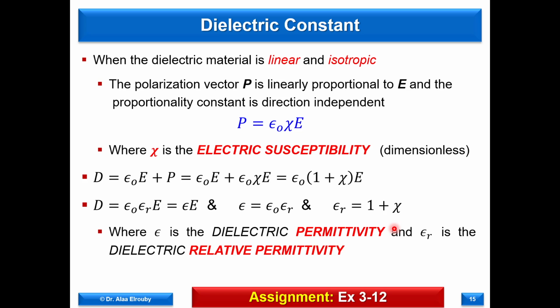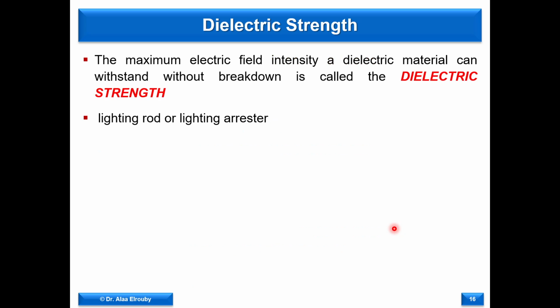So the air is a dielectric material. This dielectric material does have certain strengths. It can be an insulator up to a certain value. With the accumulation of a very large amount of charges in the clouds and with the presence of moisture in the air, the dielectric material, which is air with some vapor, will become a weaker and weaker dielectric, a weaker insulator. At a certain time when the accumulated charge is very large, there will be a breakdown.